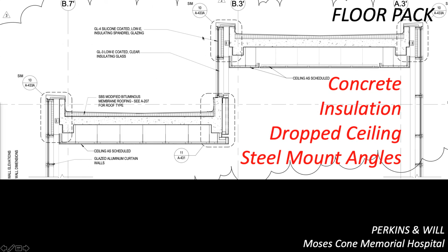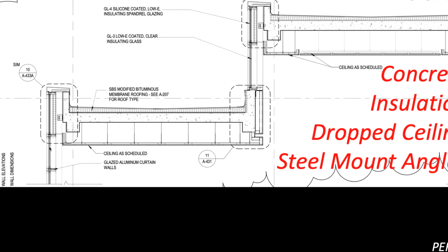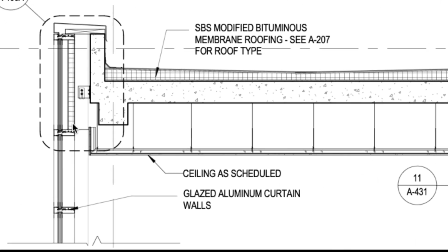And you will notice here too, we have this expression of glass, a glass wall with mullions, and we see the glass coming all the way up to the top here. So we still have mullions up here, but imagine looking through at the edge of the concrete. That's not going to be very nice. And so typically our glass up at this portion of the wall is called spandrel glass. It can be exactly the same glass as we had down below, but it has an opaque coating on the back, which basically limits view to the interior. But it will still have very much the same feel as the glass of the wall.